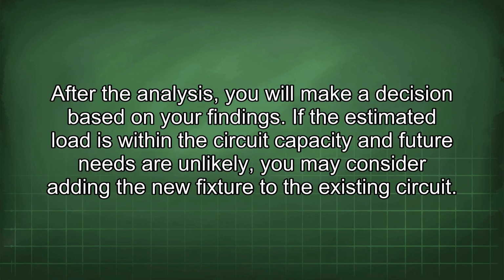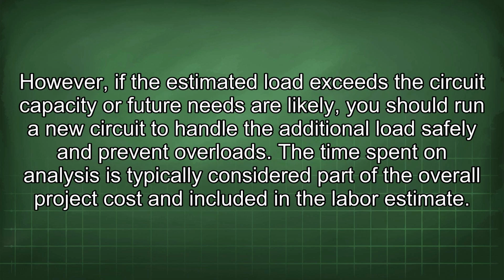After the analysis, you will make a decision based on your findings. If the estimated load is within the circuit capacity and future needs are unlikely, you may consider adding the new fixture to the existing circuit. However, if the estimated load exceeds the circuit capacity or future needs are likely, you should run a new circuit to handle the additional load safely and prevent overloads.